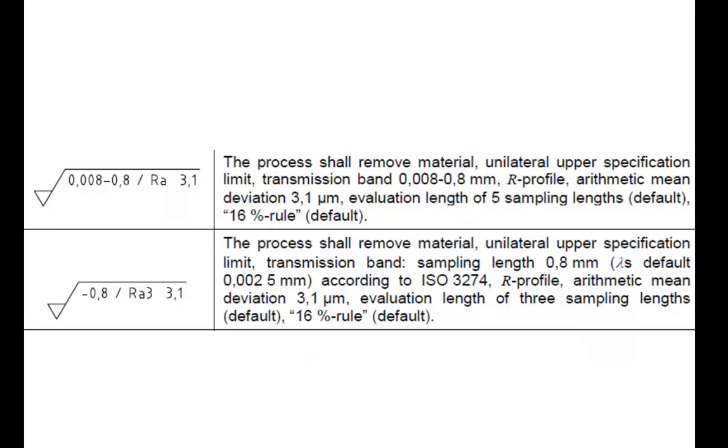It is okay. While 10 measured values are equal to the roughness value shown on the technical drawing or less, but 2 of them greater, the standard says that it can be tolerated and the surface can be considered sufficiently smooth, sufficiently good in its quality.